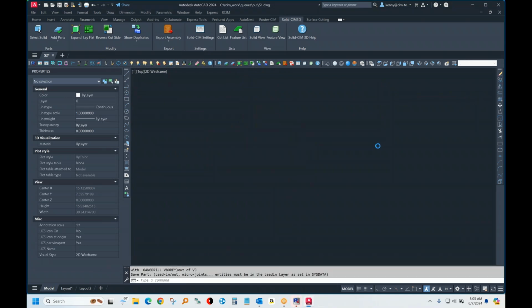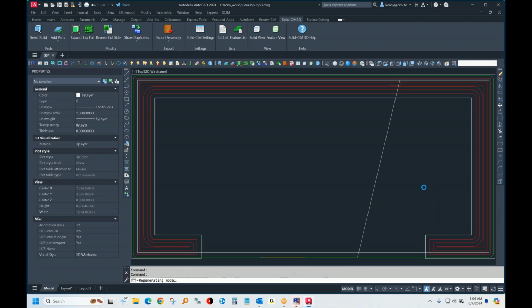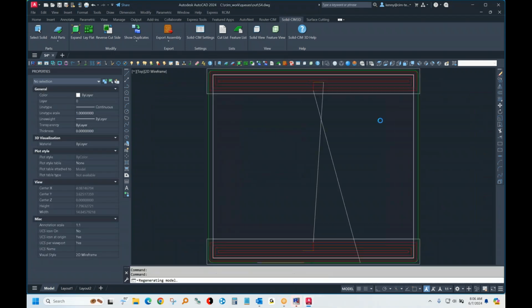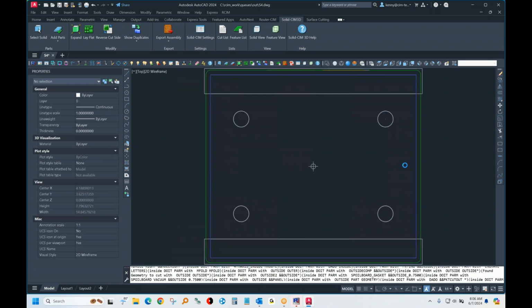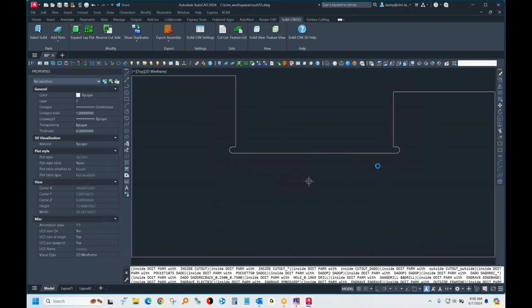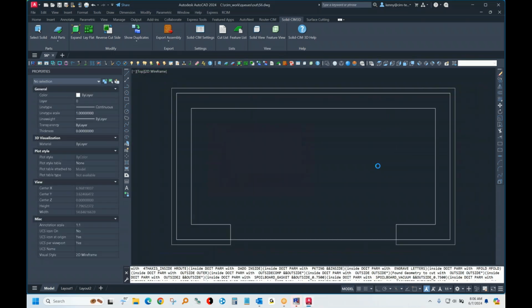We can do a corner punch to send the tool into these corners as well, so that you'll be able to fit a square part in there. You see the pockets on a different layer, they get pocketed. The drill holes on a layer, they get drilled. The outside is on the outside layer. So it makes a program for each individual piece, and then it'll make the program for the nested sheets.